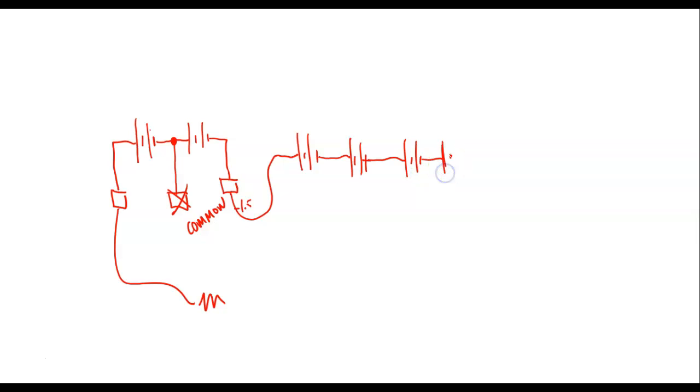So each one of these power supplies actually has two variable supplies in it, just like your trainer. That means if I can get 15 volts out of this one and 15 volts out of this one, what can I get across the two? They're in series. 30 volts. Then these are in series, so that's 30 volts. And these are in series, that's 30 volts. Well, I have 6 of these things, so I could get up to 180 volts.